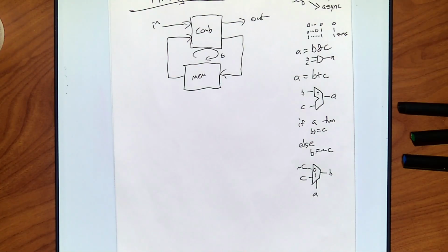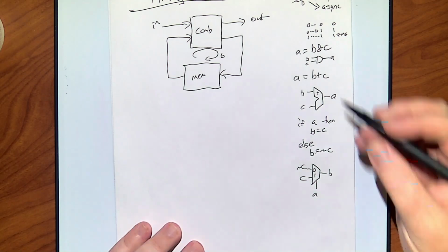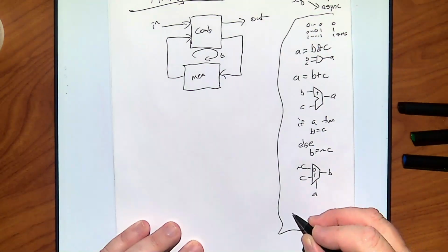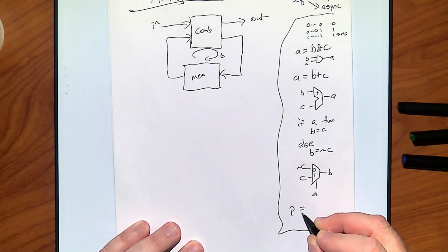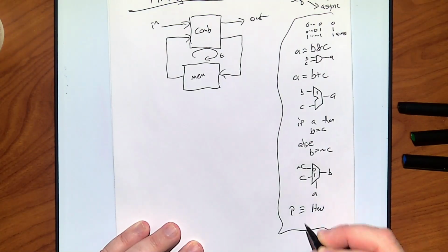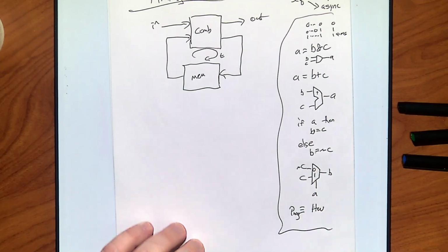On the bright side, it's going to do a lot of work for you. So this is a little bit of a notational thing for us: programs are equivalent to our hardware, and it's going to turn your program into it. When we talk about timing your design, we don't mean timing how long your code takes to run. We mean timing how long the implied circuit will take to do something.